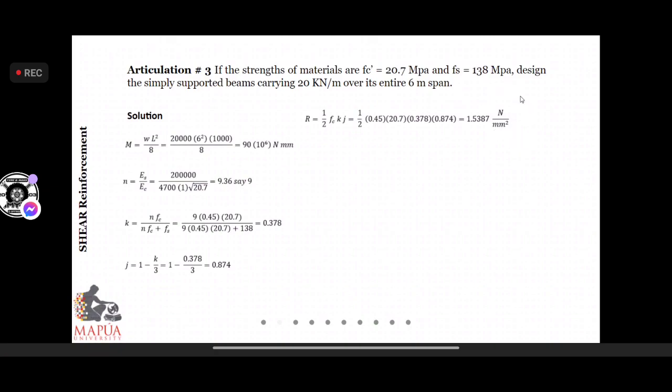This is equal to this magnitude in megapascal or newtons per square millimeter. Then we equate the moment capacity to the service moment, the product of the moment resistance coefficient, the transverse dimension, and the square of the effective depth. And we come up with the magnitude using the ideal ratio.